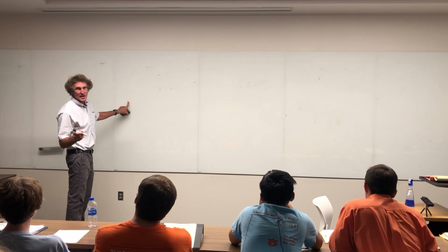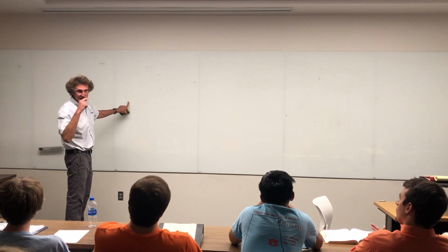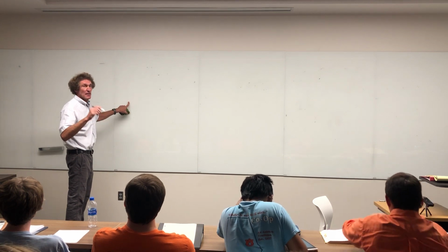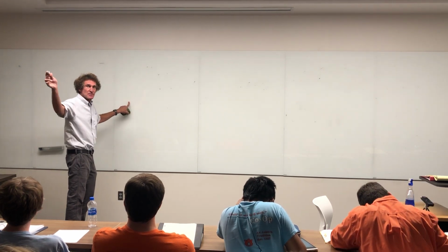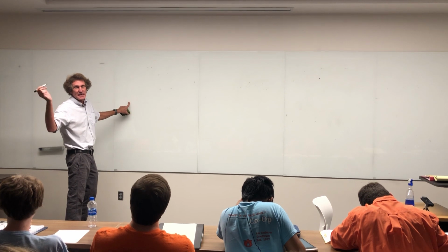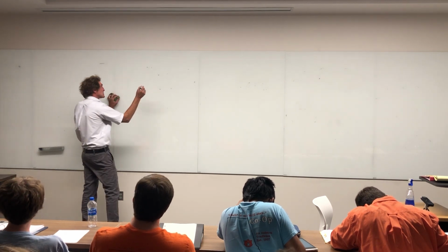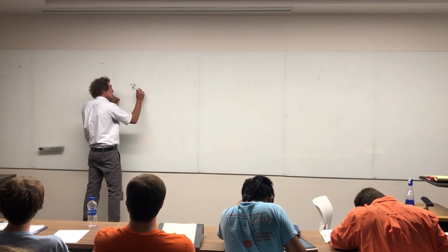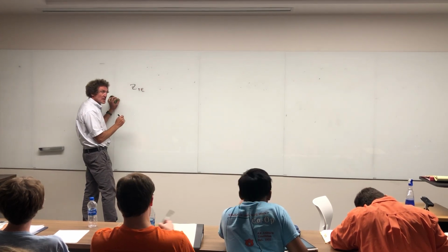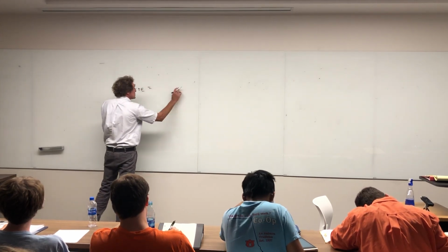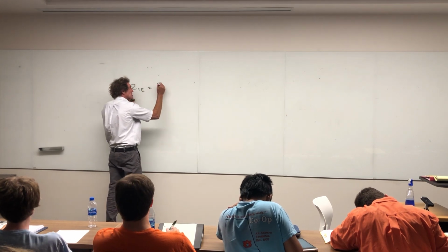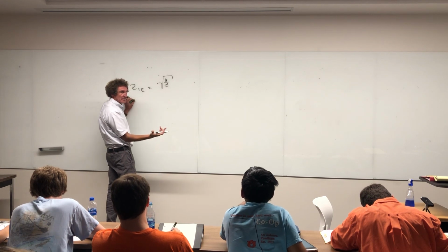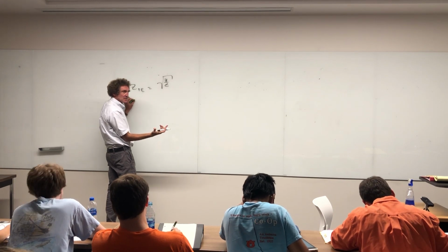So now we're going to get on to the waveguide aspects of this. Please understand the mode you operate in is usually TE10, all right? Here's the difference. Between TE and TM, there's a different impedance. So when I talk about the characteristic impedance of the guide for TE modes, it's equal to just the characteristic impedance, square root of mu over epsilon of whatever's filling the guide. That's like eta naught, understand?